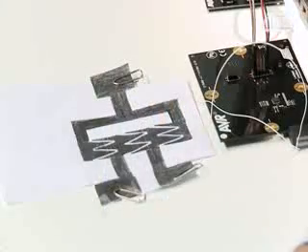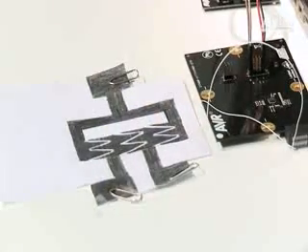At some point in your design process, you build your own target PCB and touch sensor assembly. You can still hook these up to the QT600 controller board and use its programming and data streaming capabilities. Just for fun, I'll show you how simple it is to connect a homemade touch slider. Sliderman is a piece of paper with a pencil-drawn 3-channel slider sensor drawn on it.